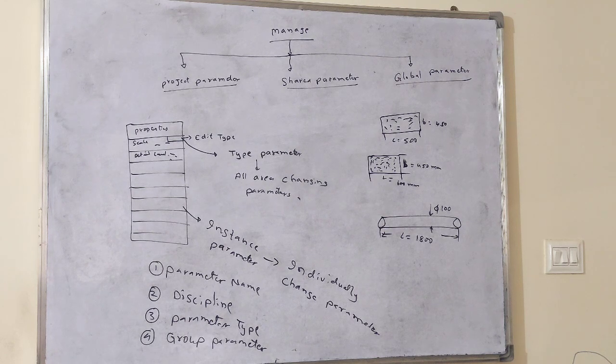Now if I select this grid again, you can see there is extents, and here IFC parameters. These are the headings of the parameters. This heading we call group parameters. And whatever names you find here, such as scope box, name, export to IFC, GUID, these are the names of the parameters.